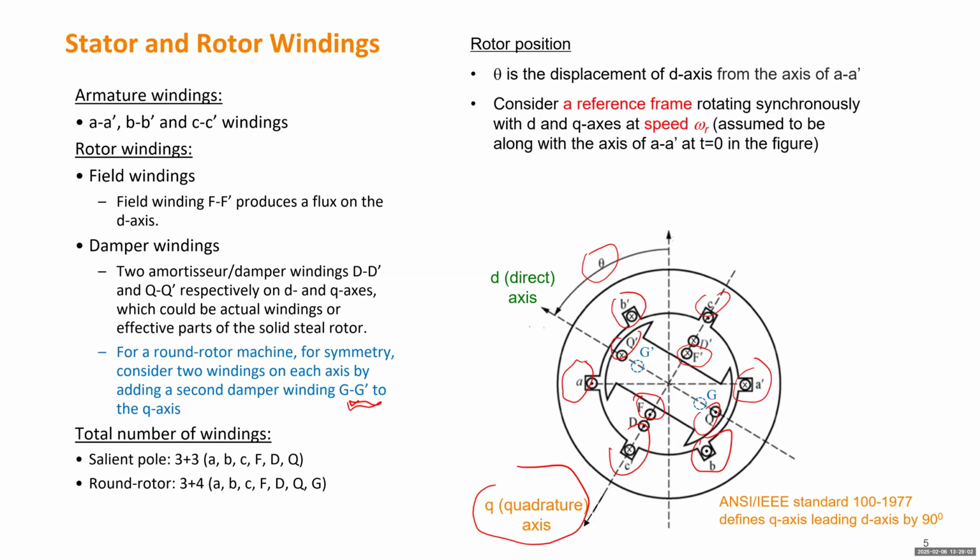But it's not very convenient to categorize the position of the rotor, because in reality, nobody can look inside of the rotor to see where the D axis is really facing. And that's not important at all, because, as I said in the last section, if we talk about rotor angle stability, it's important to have 2 rotational masses, which means 2 synchronous generators. If the 2 angles are always pointing to the same direction, the 2 generators are synchronized perfectly. But if one angle is separating from the other, and the angle keeps increasing, one generator may become unstable.